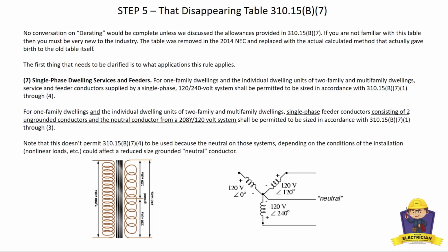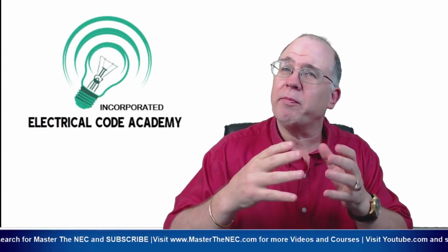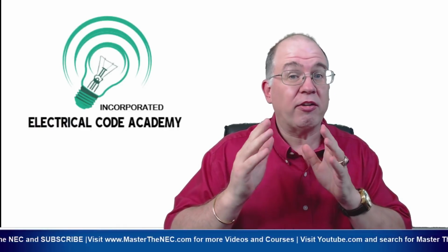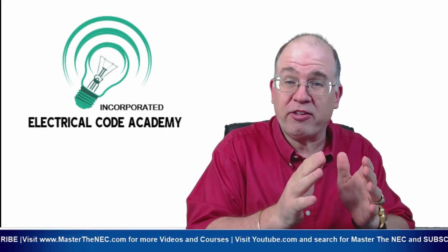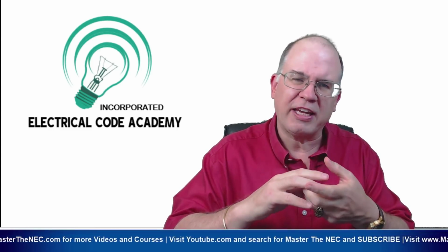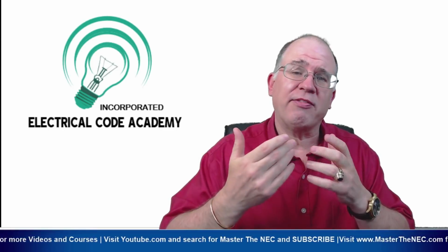Now, again, this used to be a little table based on an old rule where it's 84% of the values in 310.15(B)(16). But they decided to use 83% for the 2014 cycle where this came about, and they started to use a calculation. Now, a lot of people say they've made this confusing because they should have just left the table in.